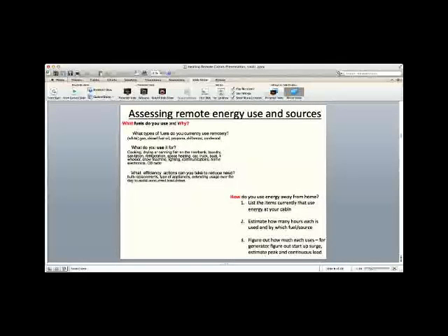Well, you can be sure to do some of the same things that you do at your home. You can put up rubber threshold around the door, and then maybe even a blanket over that to try to keep a lot of infiltration of air. A lot of people in cabins use small windows compared to their home windows, because a window does transfer heat through the glass, even if you have a buffer zone in a dual pane or a tri-pane window.